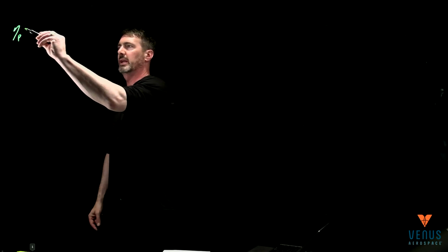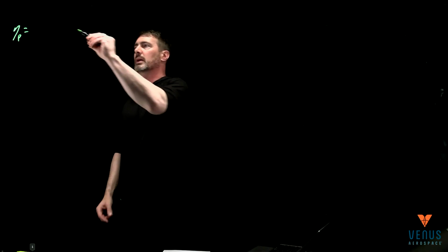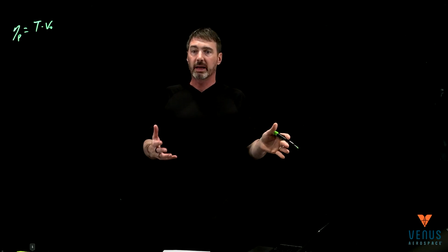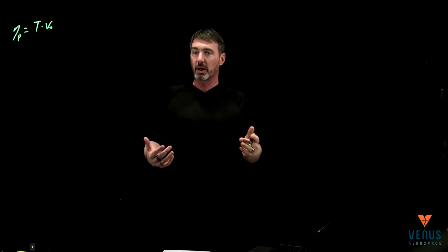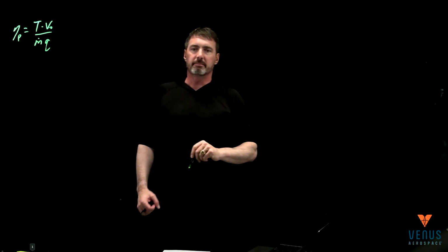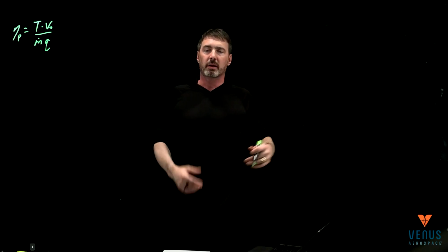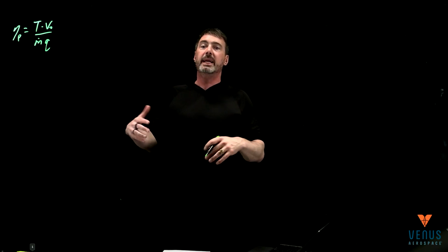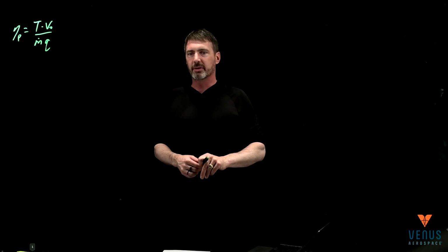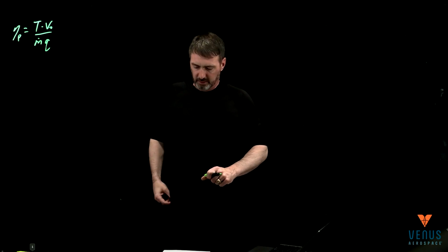In the end, the thing we want is thrust, or thrust power. That is the thrust force times the velocity that I'm flying at. And what did it cost us? Well, it cost us m dot times Q, where Q is the heat added and m dot is the mass flow we're adding it to in the air. That represents the heat addition, burning our hydrocarbons, or burning our hydrogen if you're carrying hydrogen. So that's what we're looking at in terms of cost.